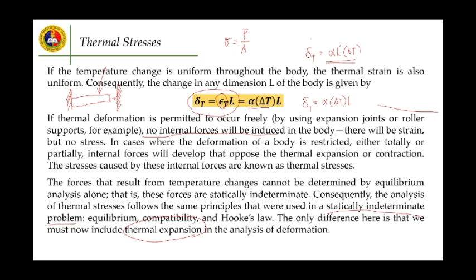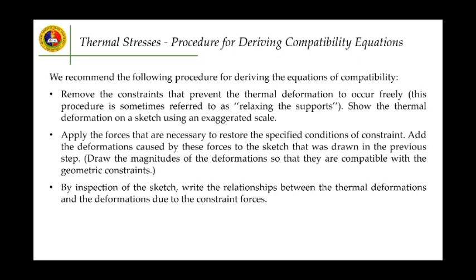So basically, that's the analysis part for thermal stresses. Now, there is a guiding procedure as to how to derive the compatibility equations. First, remove the constraints that prevent the thermal deformation from occurring freely. This procedure is sometimes referred to as relaxing the supports.